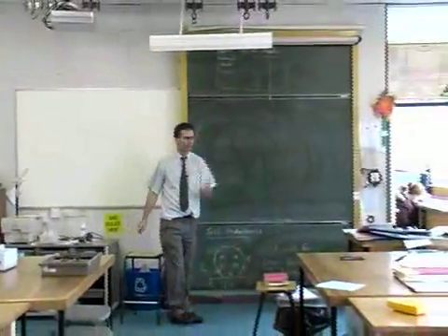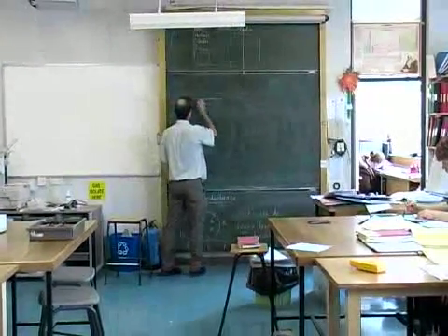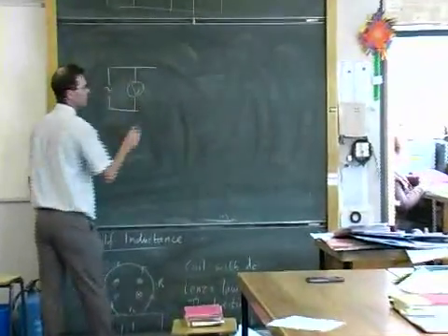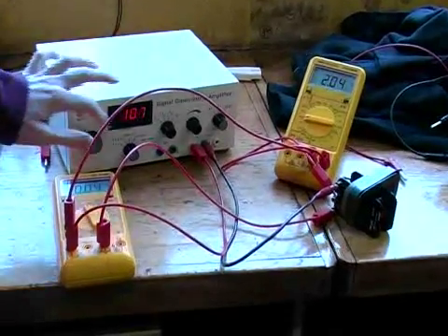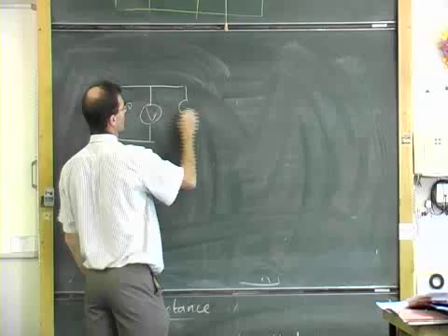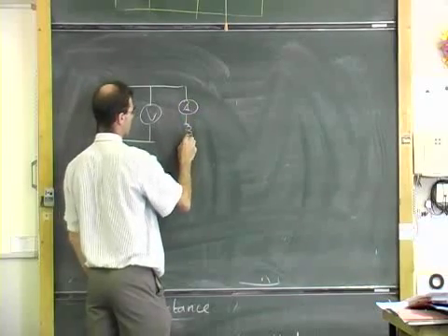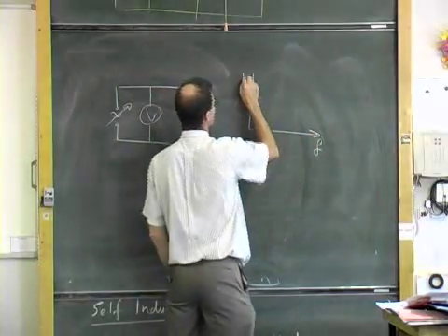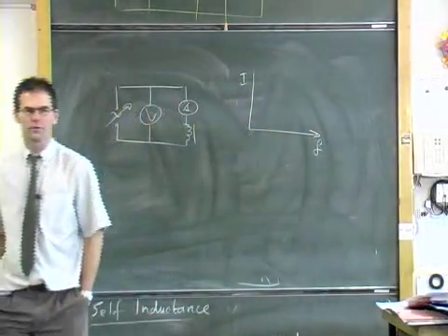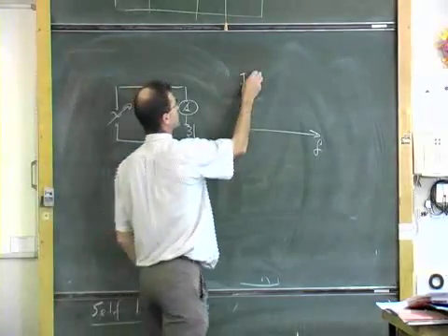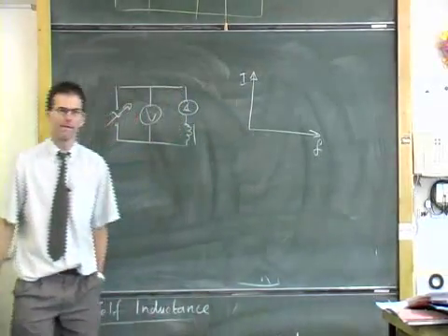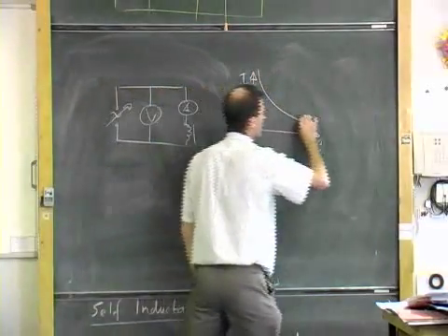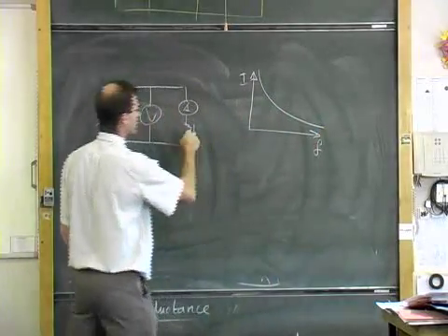What you've been able to do by setting up a circuit where you've got a source of alternating current, you've monitored the voltage and kept that constant, and we've seen what effect changing the frequency has on the current running through the inductor, and you've plotted frequency and current. Well, in fact, some of you didn't even need to plot that, because what kind of shape were you getting as you increased the frequency? Ben? Okay, so it comes up like that and goes down like that. As you increase the frequency, we're finding we're getting less and less current going through.